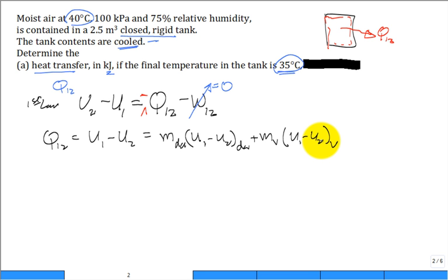I don't know if it all stays in the vapor form. What of the three temperatures can I compute to see if it will condense or not, and compare it against this 35 degrees C? You calculate the dew point temperature, and it's around 34.5 or something. Let me look at my notes. 0.5 degrees C. So do you expect anything to condense? No, the temperature's above. So this is a good form to write where it all remains vapor. Part B, guess what we're going to do? We're going to cool it below the dew point. But let's do part A first.